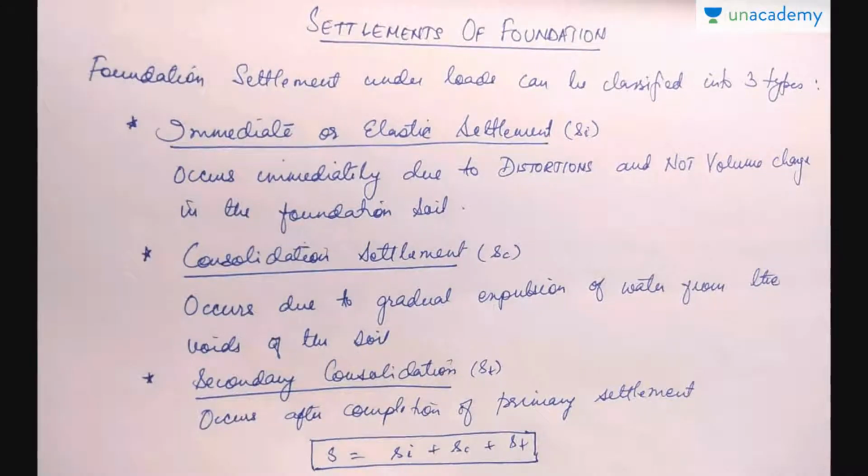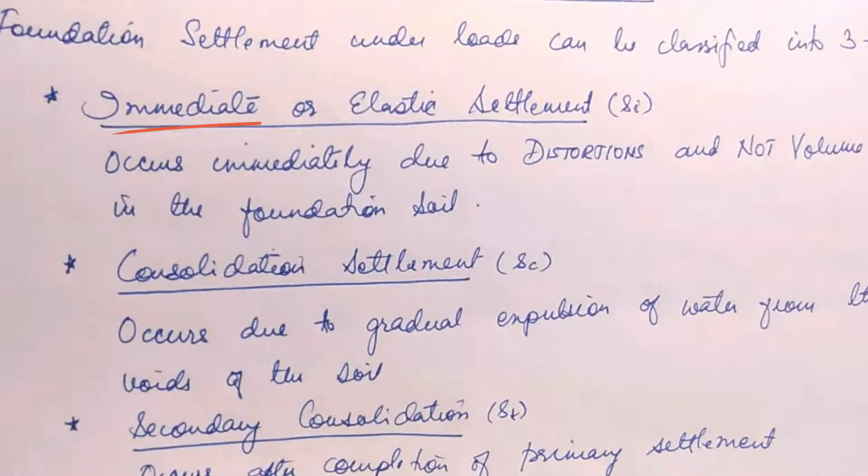And this lesson is all about settlement analysis. Foundation settlement under loads can be classified into three types. First one, intermediate or elastic settlement denoted by SI.